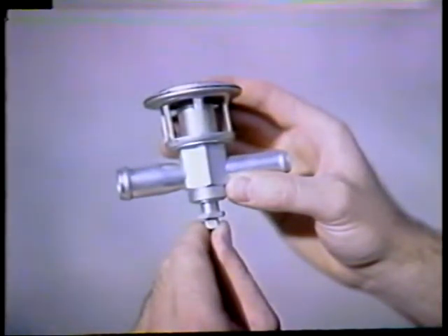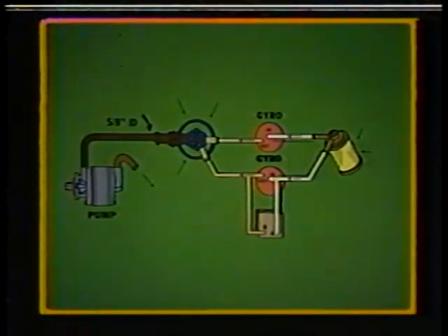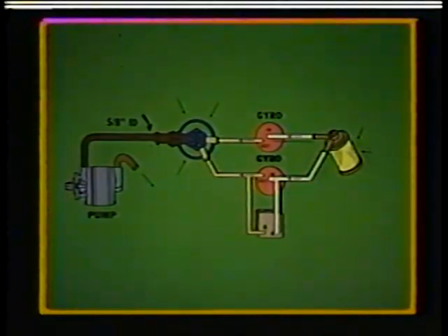In addition to filtration, the airflow produced by either a vacuum or pressure pump must be controlled. This is achieved by installing an adjustable flow controller. In a vacuum system, a relief valve is installed between the pump and instruments, so a constant low pressure or vacuum is maintained on the instrument side of the valve. This is accomplished by allowing filtered air to enter the system when the pressure is below that for which the valve is set.